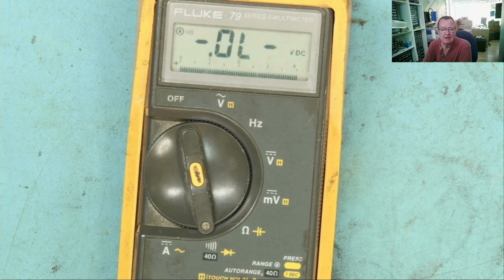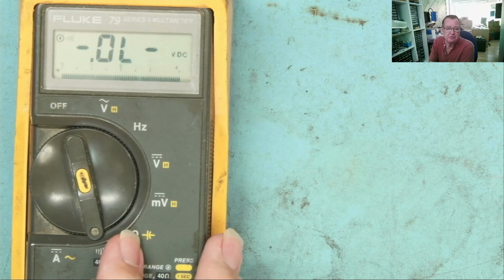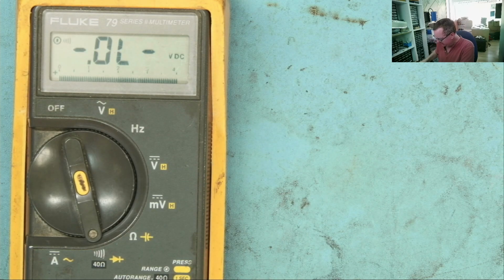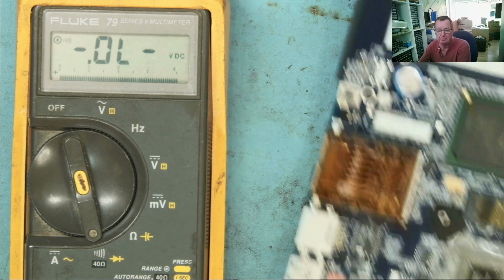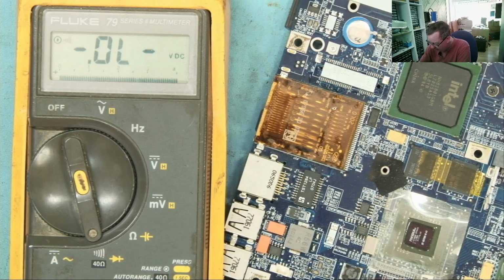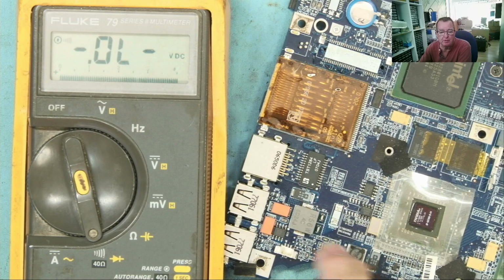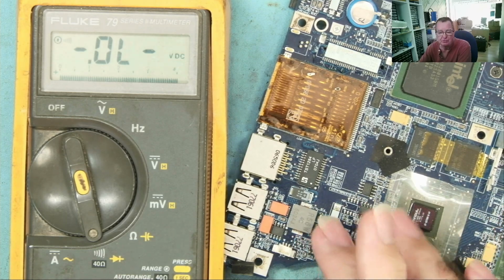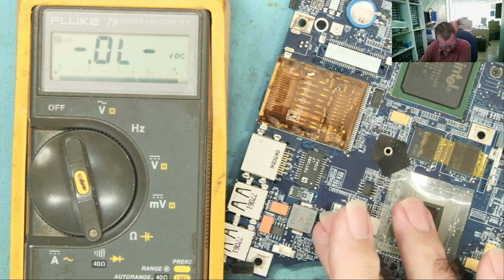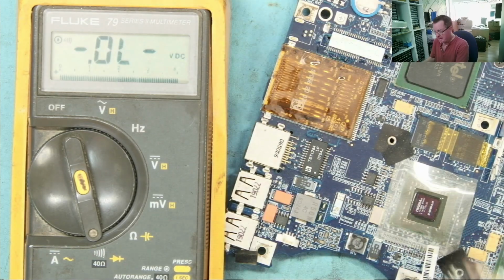Let's have a look at situations where we shouldn't use diode mode. We should use resistance mode, or at least it's better to use resistance mode. Okay, so the situations this normally occurs in is things like laptop motherboards, desktop motherboards, graphics cards, and these sort of things, where you have a lot of buck converters. You can recognize them because you'll see these coils. Sometimes they look slightly different to this, but you'll see coils on the board. We can have another board.